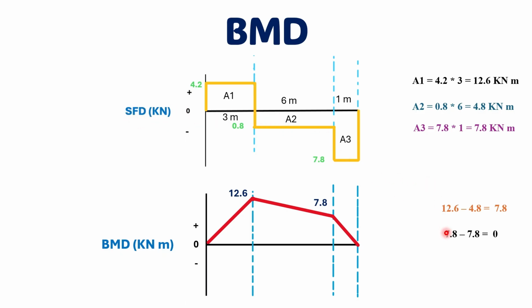So I hope you got the concept behind how to draw the shear force and bending moment. With the help of the free body diagram of the beam, we can draw the shear force diagram, and with the help of this shear force diagram we can easily draw the bending moment diagram.